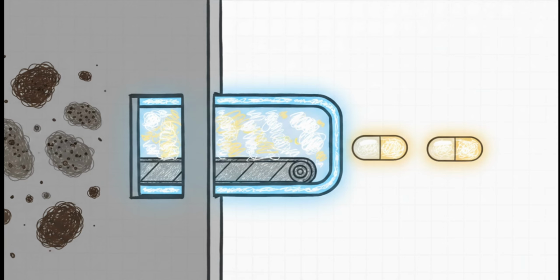For example, the EU GMP guidelines state that a conveyor belt cannot pass through a partition between a high-grade clean area and a lower classification area unless the belt itself is continuously sterilized, like, say, passing through a sterilizing tunnel. The architecture dictates the process, not the other way around.